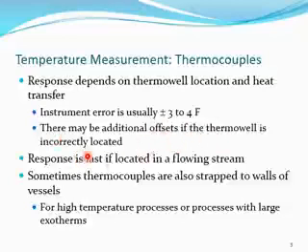If the thermocouple is incorrectly located, it will not sense the right temperature, and the voltage will not be generated properly. The response and voltage generation is fast when the thermocouple is installed in the flow stream, in the place where there is flow.